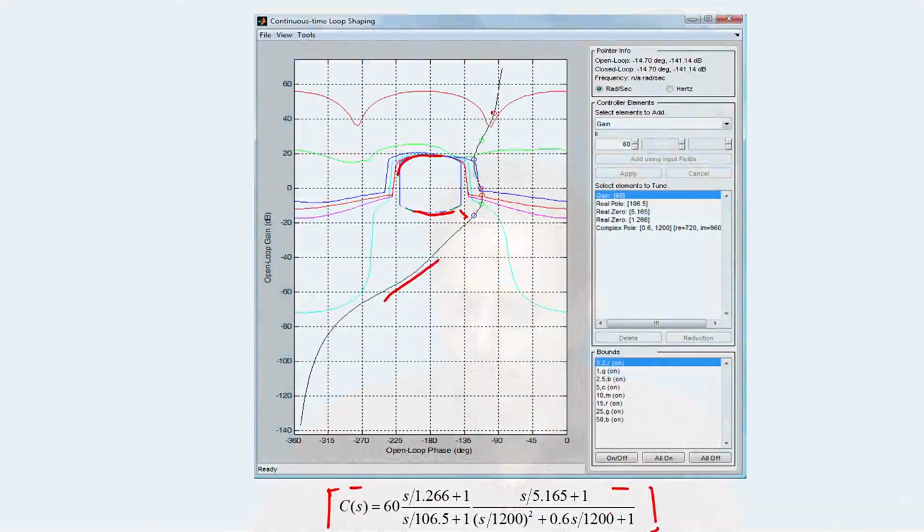So this completes the design of the feedback controller, and this feedback control structure, which I said we could obtain by trial and error using the interactive dialog box that is available as part of the QFT software, gives us the performance necessary to restrict the variation of the transmission function due to uncertainty in the plant parameters, and at the same time ensure that our feedback system is stable by the specified amount.